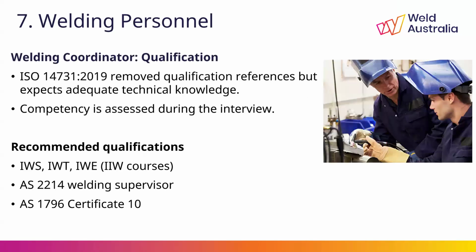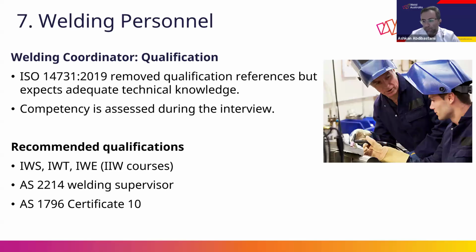Thank you. Yeah. And so there is no mandated qualification for welding coordinators under the current edition of ISO 14731, but courses like IWS, International Welding Specialist, IWT, International Welding Technologist, or IWE, that's the highest level, International Welding Engineer.